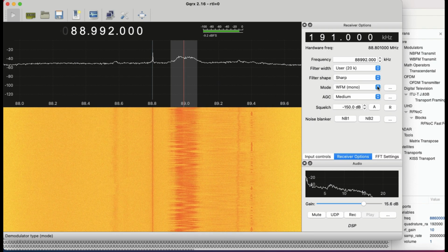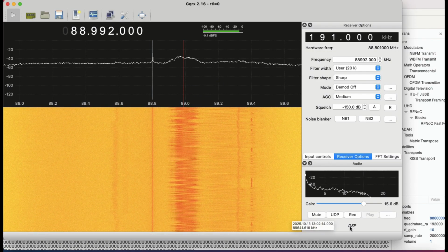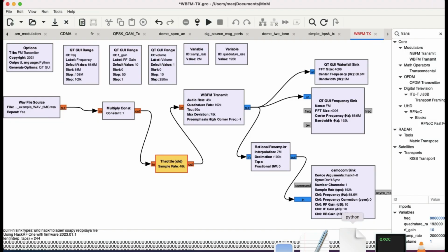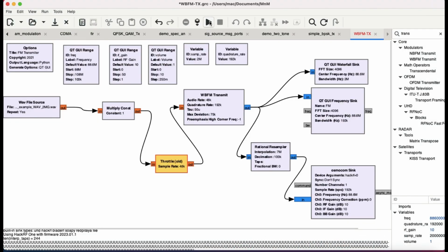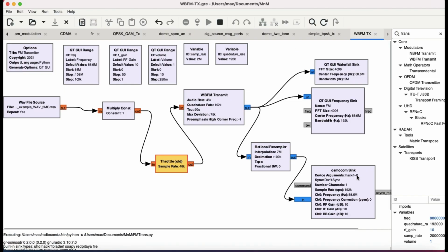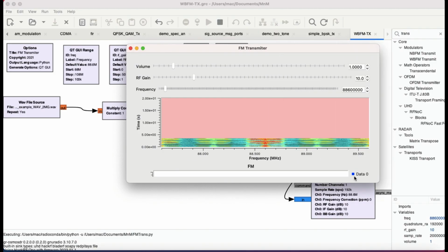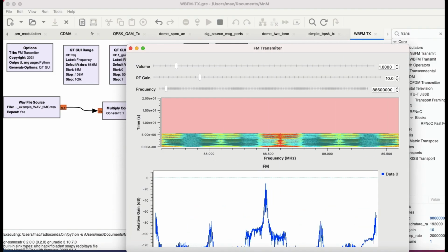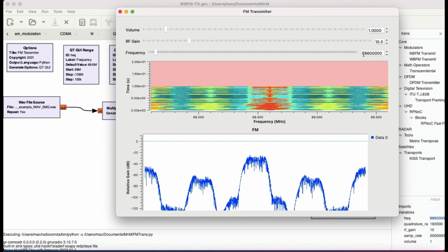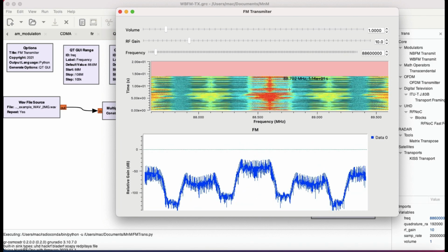Now I'm going to turn off my demodulation, and I'm going to transmit this audio file using my GNU Radio. So let me just simply hit transmit. It's going to start transmitting this using Osmocom source, which is actually HackRF. And this is what it looks like, what's being transmitted. So this is your waterfall graph. We're transmitting at 88.6 megahertz. This is where I'm transmitting the signal.